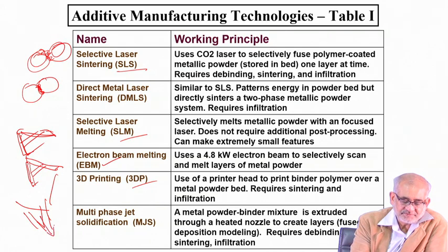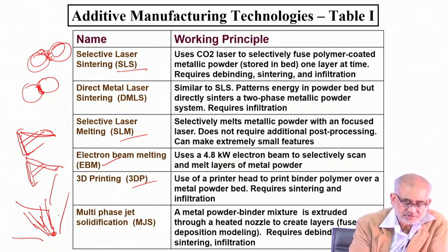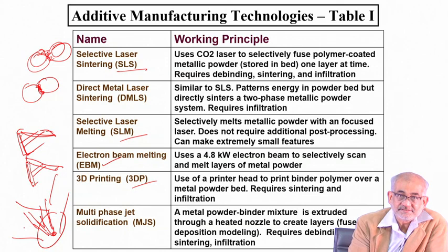So if the laser beam is incident here, the powder can also come in a concentric manner to the same focal spot. This is a lot better than having laser and powder coming from two different directions. This is fairly possible. In fact, these days with a fiber laser delivery system, this kind of possibility has become extremely feasible.